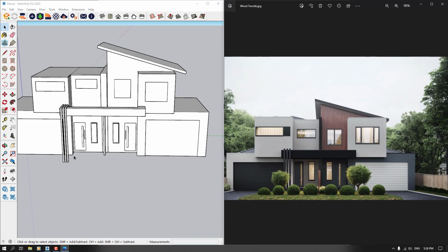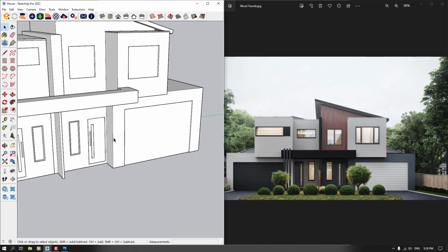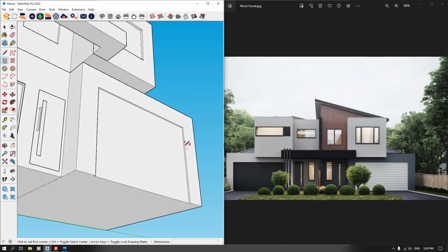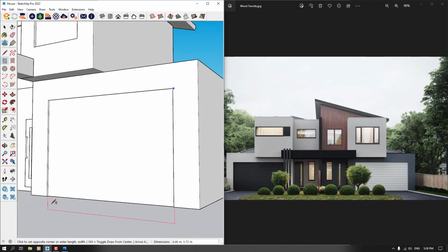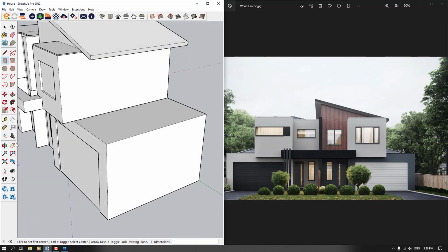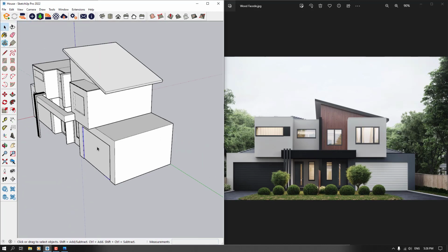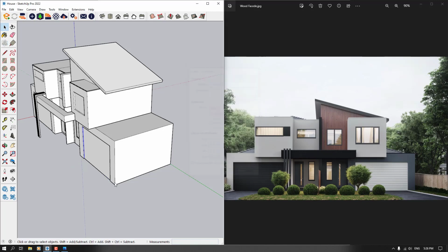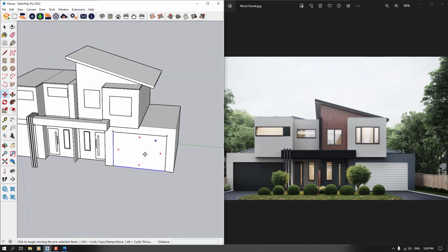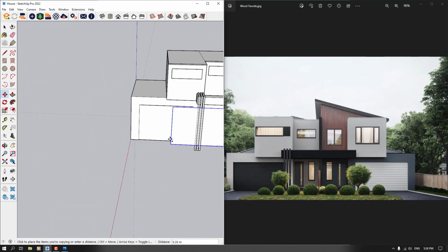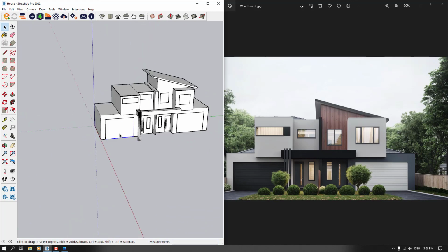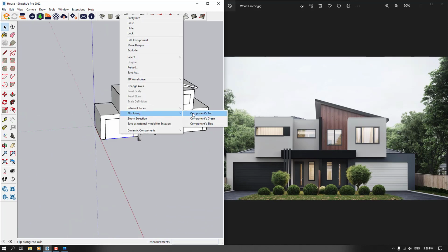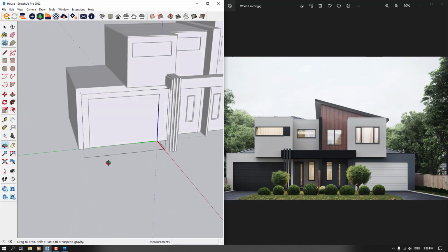garage doors. So I'm gonna use rectangle again. Rectangle is the best useful option in the SketchUp. I'm gonna click on it, make some group. I called it parking door, like this. I press enter. I'm gonna make some copy of it from middle point to middle point and flip along it on the green direction.